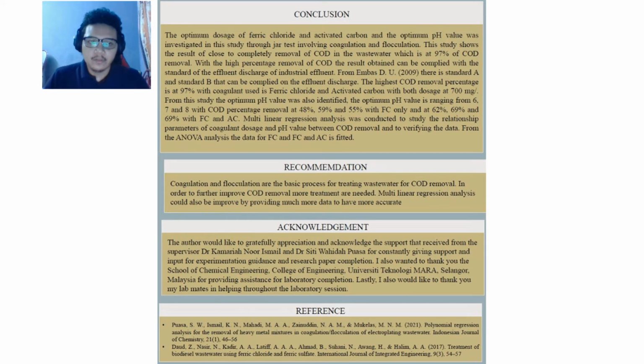From this study, the optimum pH value was also identified, ranging from 6, 7, and 8, with COD percentage removal at 48%, 59%, and 50% with ferric chloride only, and at 32%, 69%, and 69% with ferric chloride and activated carbon.